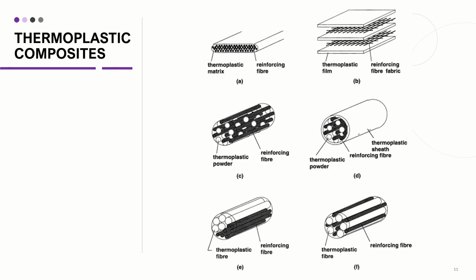Most blades are manufactured from thermoset composites, which have specialized curing requirements and cannot be easily recycled or repaired. Thermoplastics therefore offer several advantages. Since they soften when heated and reform upon cooling, thermoplastics allow for the use of fusion welding and adhesives. Defects can be directly repaired during the manufacturing process. Additionally, curing ovens are no longer needed, reducing production energy usage by 95%.